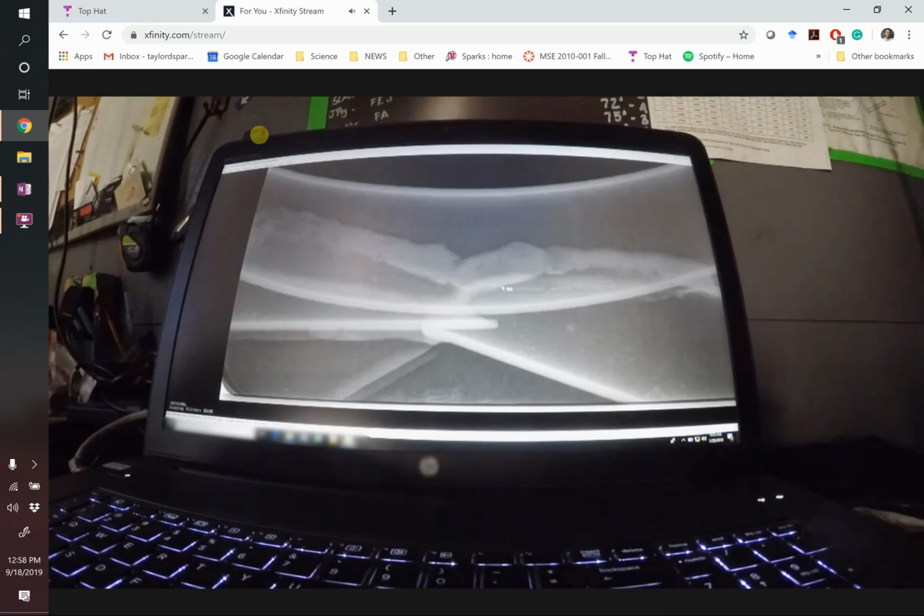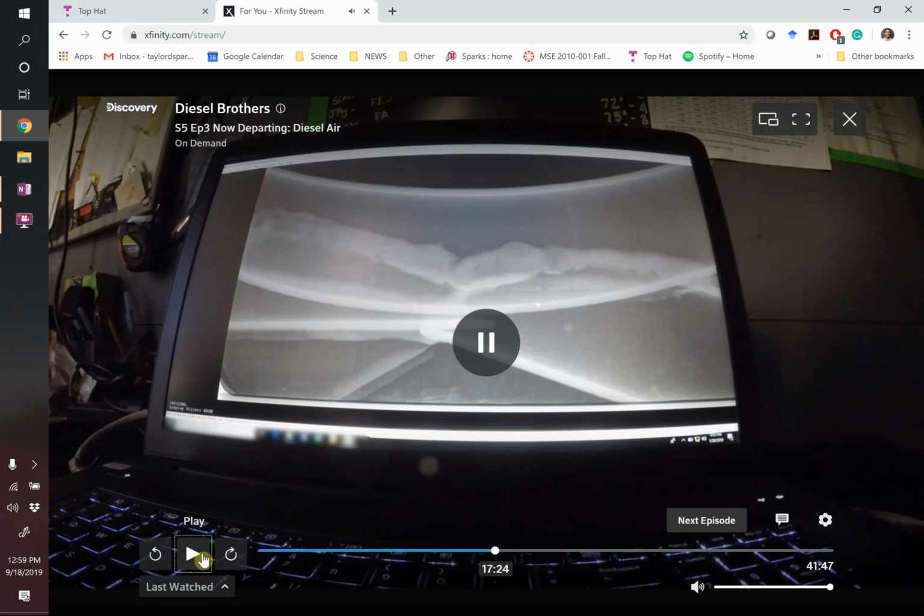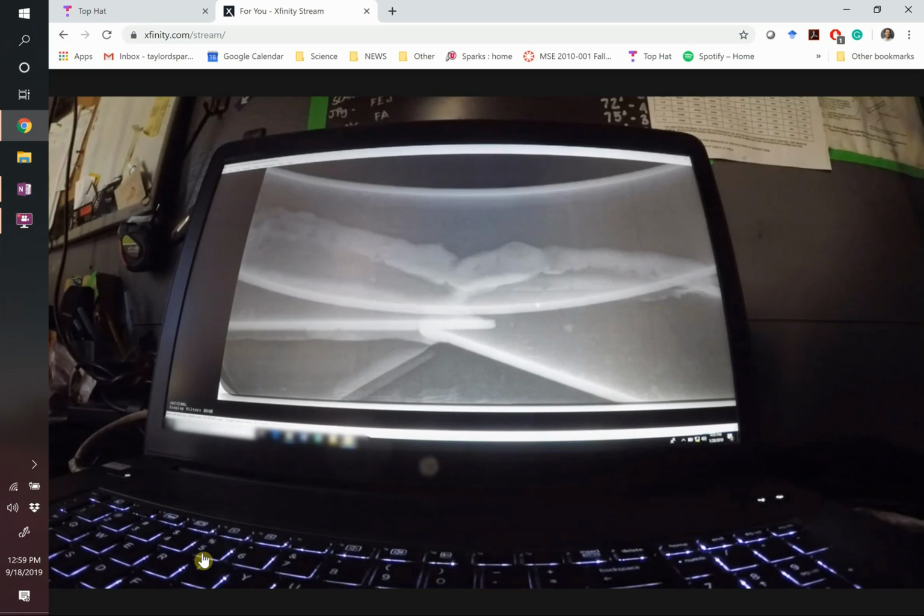But what they do here is they're able to visualize each one of these welds where they come together because they take a little plaque that is sensitive to x-rays essentially. They shine x-rays on it just like when you go to the dentist, right? When you go to the dentist, they've got that awful thing that they put in your mouth, and then they've raised the camera right next to it and they snap a picture. And what it's doing is it's bombarding your face with x-rays, right? And x-rays are able to pass through a lot of materials, but they get slowed down or absorbed by some materials. Like in your teeth, if you have a nice healthy tooth, it should be absorbing x-rays. But if you've got a hole in your tooth, right, a cavity forming or a crack or something, they can see that because the x-rays go right through it.